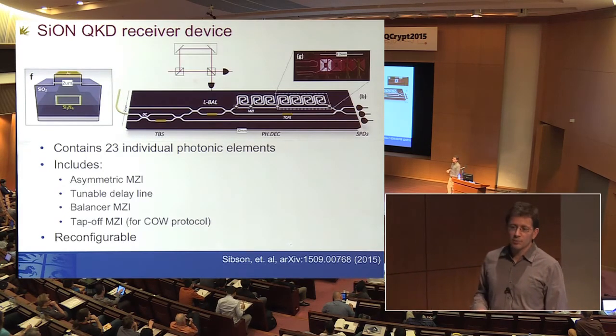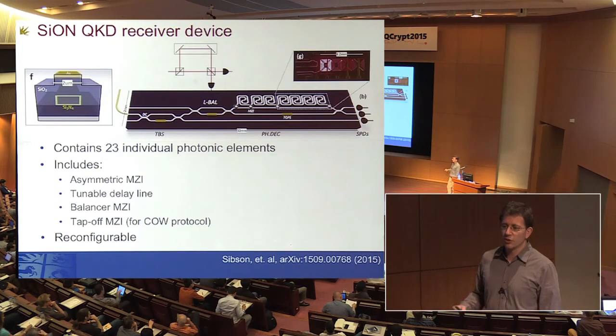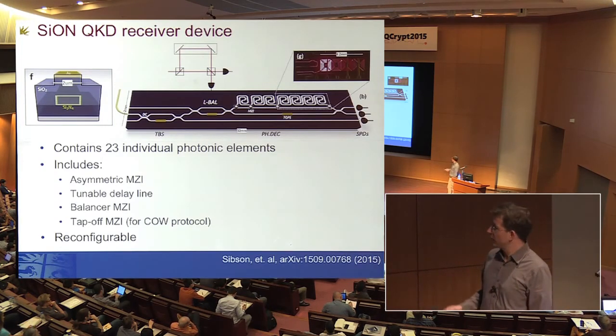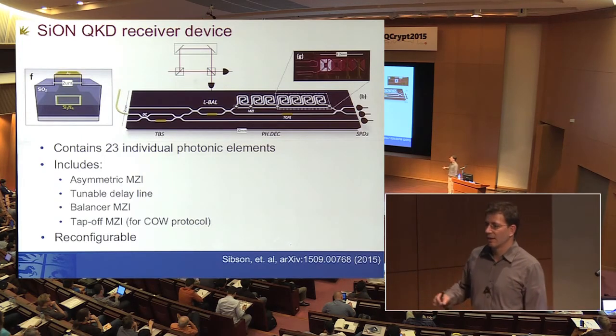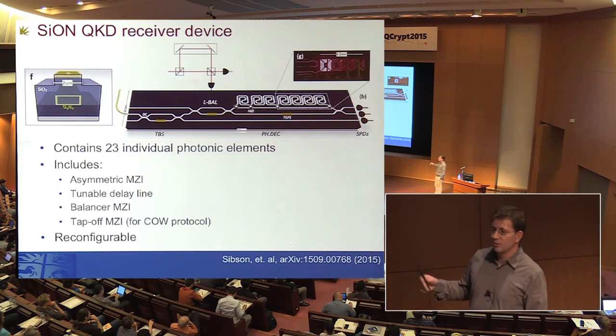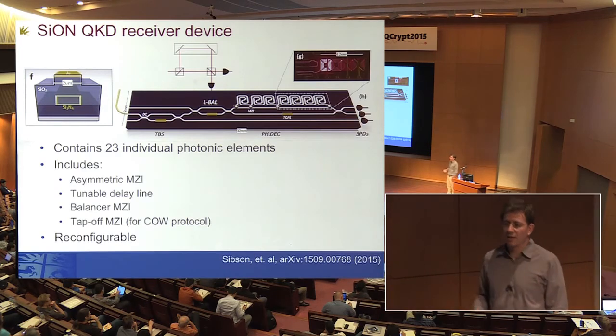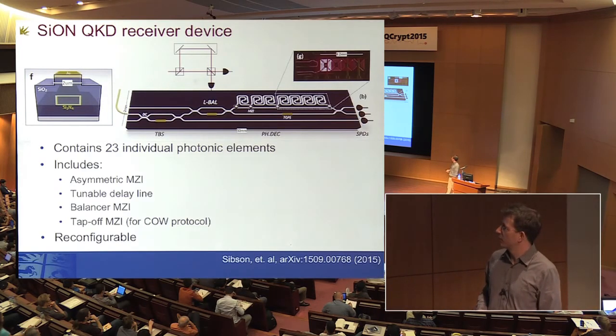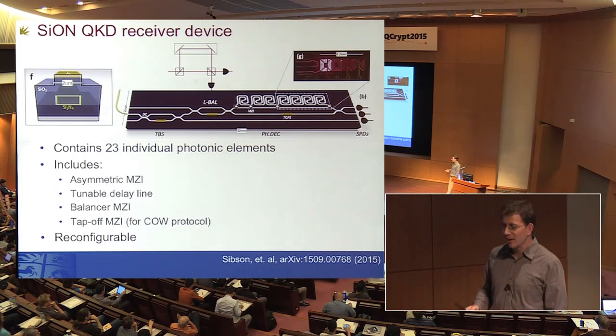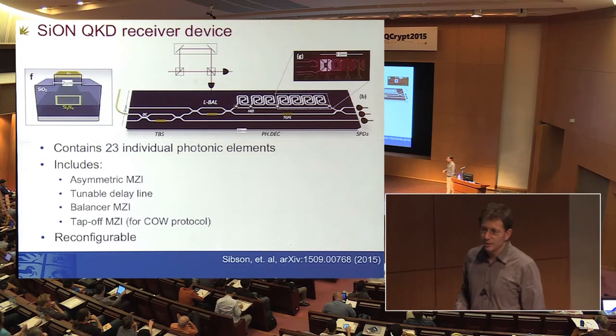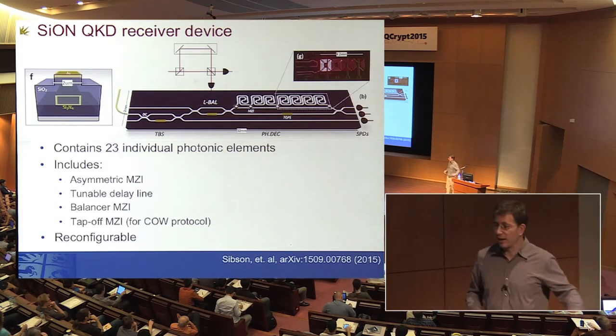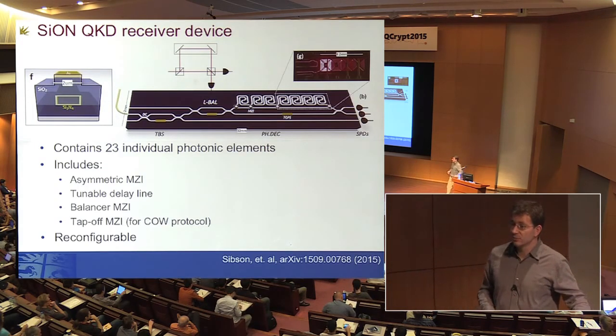It is possible. There are proof of principle demonstrators of on-chip isolators. The problem is you need effectively a material with a magnetic susceptibility that allows this kind of non-reciprocal interaction with the light, which is a very difficult thing to realize. So people have realized them, but they're lossy, not very practical, and not readily available. So we have absolutely no plans to put isolators into these systems.